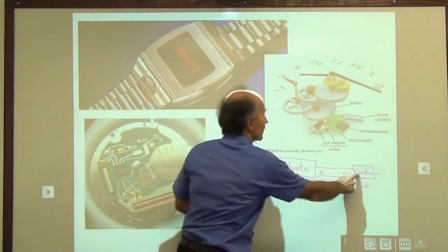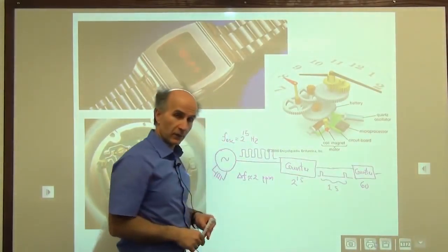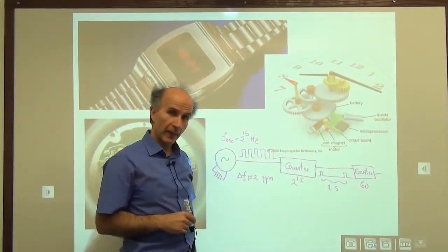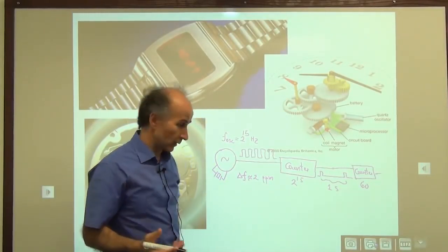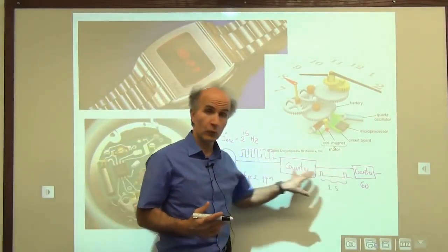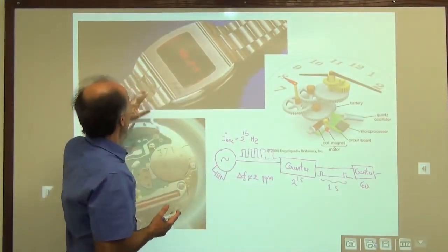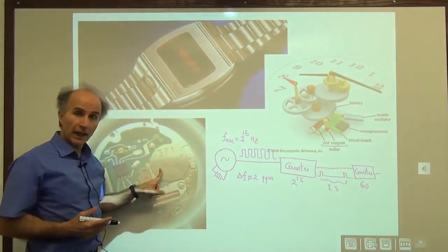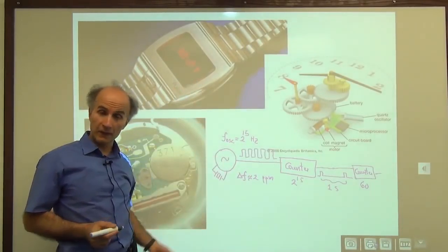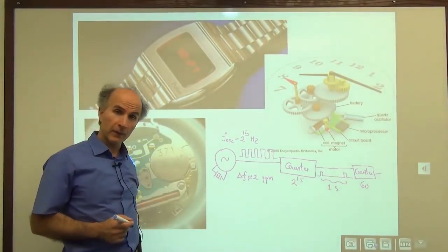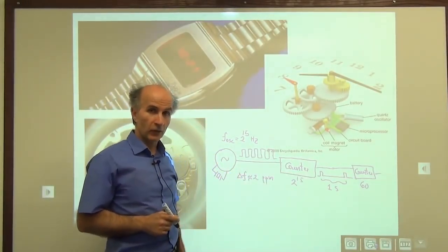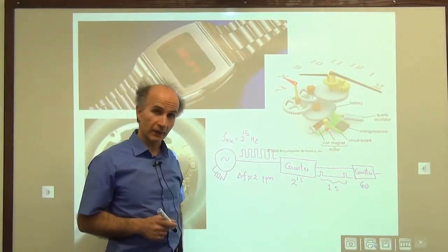So all of these counters are inside this so-called microprocessor. In olden days, this was not really a microprocessor, but just a few counters. And the enabling technology for all of these was CMOS. Because without CMOS, these would consume too much power. And you could not possibly have a watch run from a little battery and last a long time. With my watch, I change the battery once every 4 years, 5 years. So that's a very, very small power dissipation for having an oscillator and some counters, etc. So that's the beauty of electronics, even as early as 1970s.